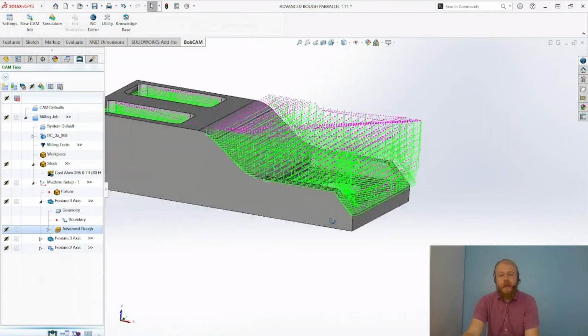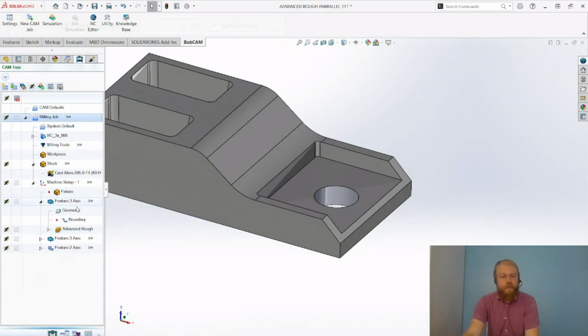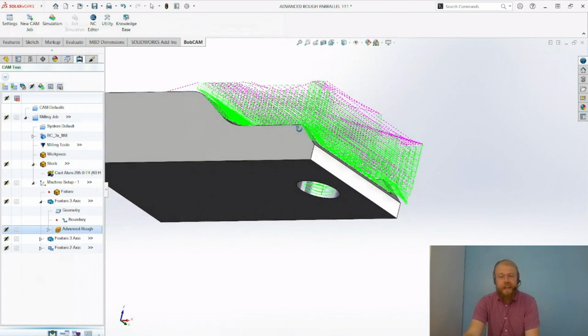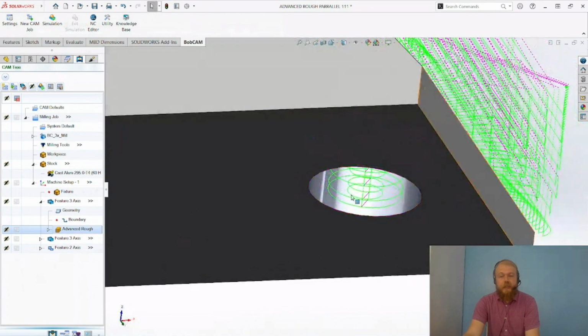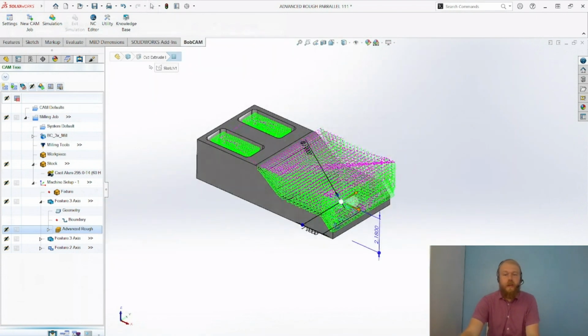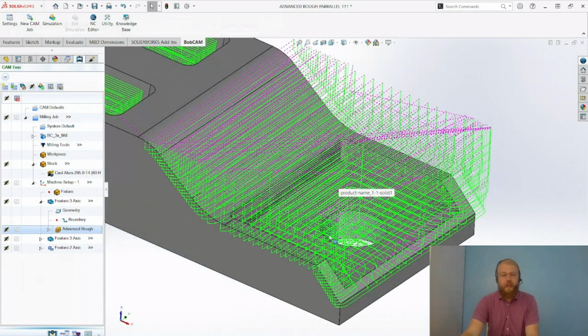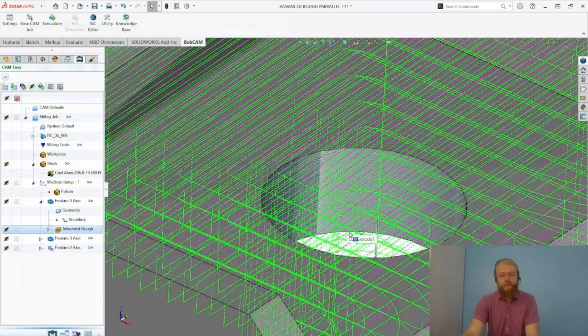So that really helps out. Instead of having to create a new milling job, or even delete the operation here and then create a totally new operation based on the new geometry changes, you don't have to do that now. You can go right into the CAM tree, and it will automatically update the geometry. Then you just compute the toolpath for the new geometry updates.